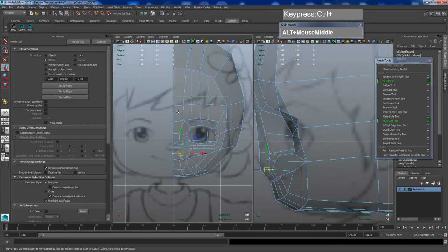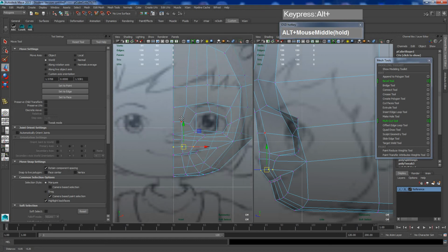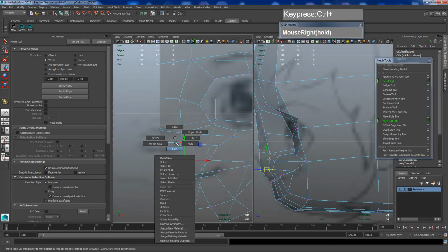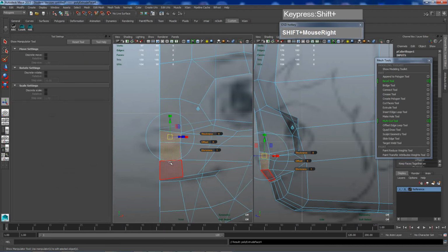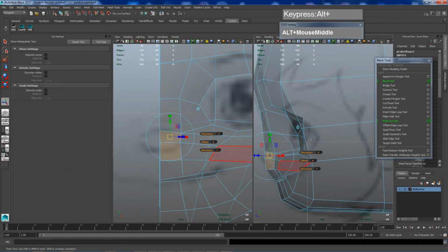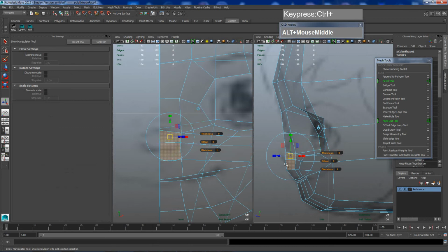Okay, I already did the reflow earlier on, by cutting, so I have sufficient faces, one face here and one face here, to create the nose. So I'm going to hold down the shift, right mouse click, and extrude the faces. And this time, instead of using the local axis or the normal axis, I'm going to click on this switch button here, and then push out the nose in the global axis.